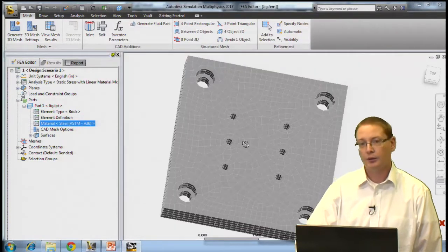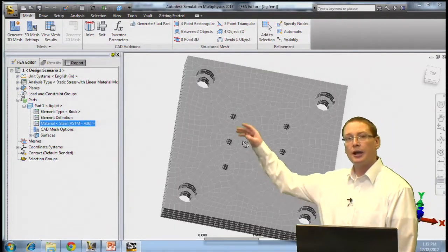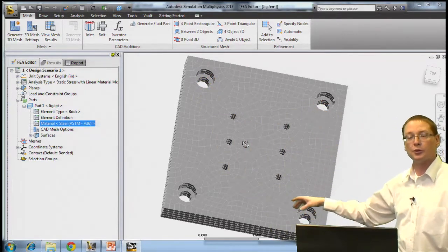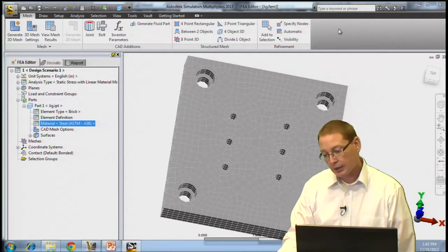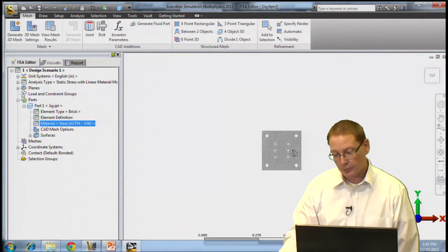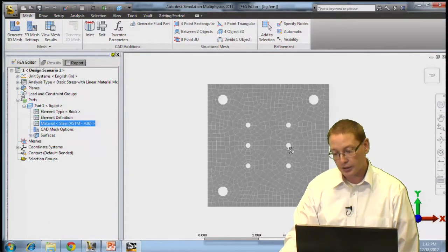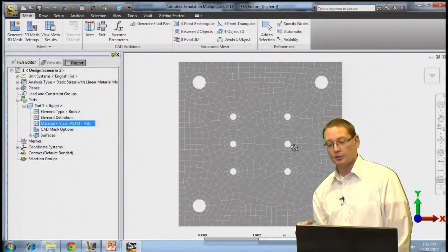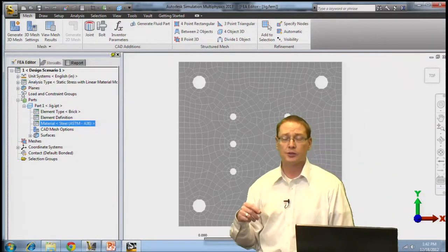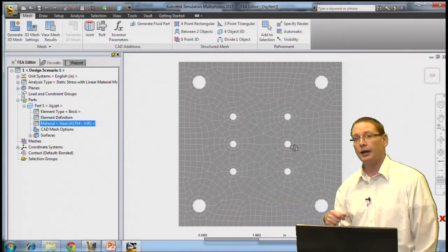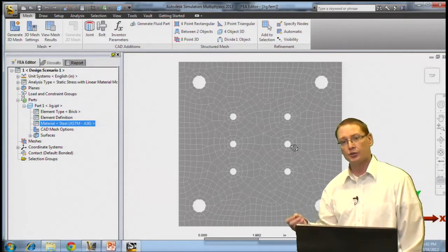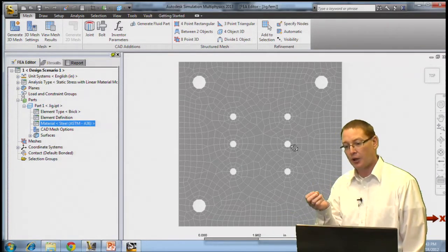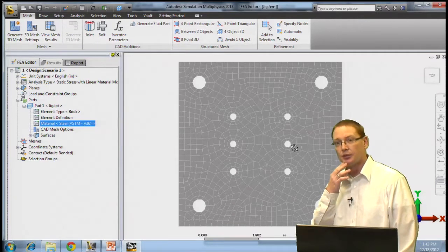and we'll say OK. All right, so looking at this geometry, what I had envisioned is that we're going to hold the piece down by the 4 bolt holes in the corners. So I'll add those constraints on. Now that we're getting to the point in the setup where we're actually looking at loads and constraints on the model, here is one of your considerations. I already know for the purposes of this particular demonstration that we're going to go back to Inventor, we're going to make some change and we want to bring it back in. Ideally, what I would like is to have as many loads and constraints remain on the model after doing so as possible. So there are multiple ways that you can add loads and constraints inside simulation.